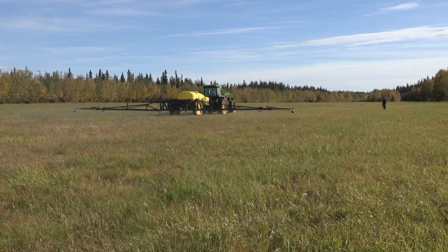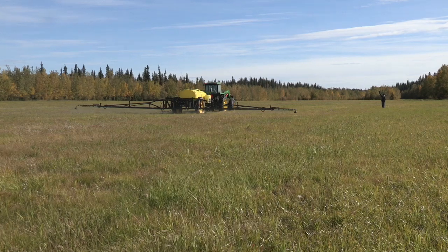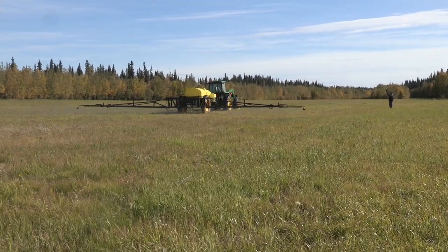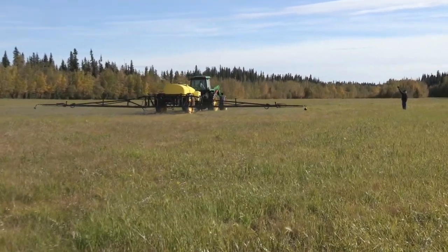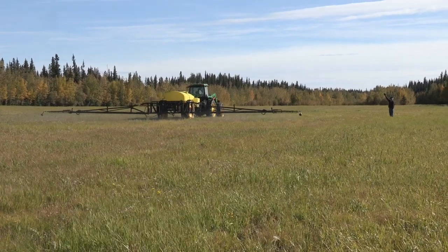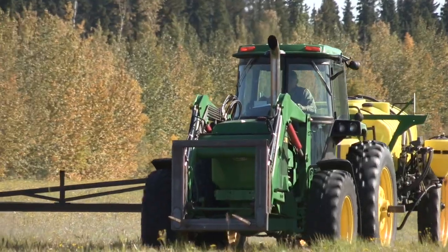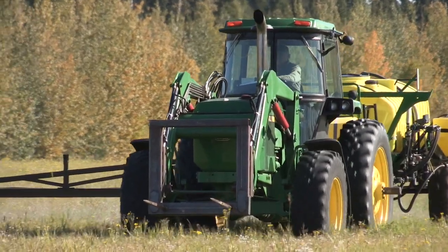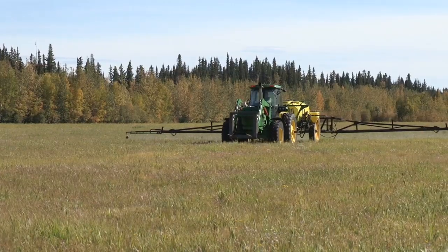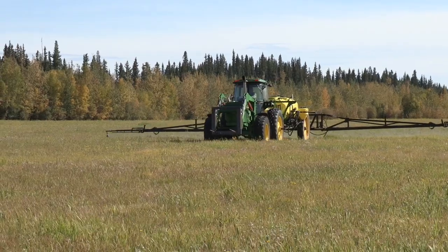You will want to have the sprayer functioning as you intend it when you are in the field, with pressure set and all booms on. Having an assistant for this part can make it easier and more accurate. Consistency of speed is important here. Do this timing several times and determine what the average time is.